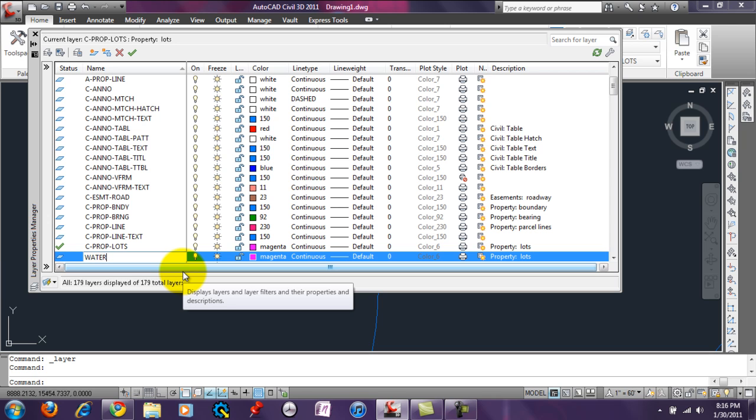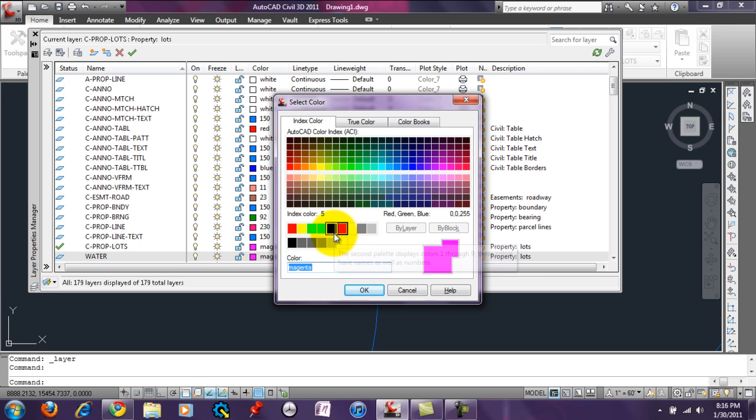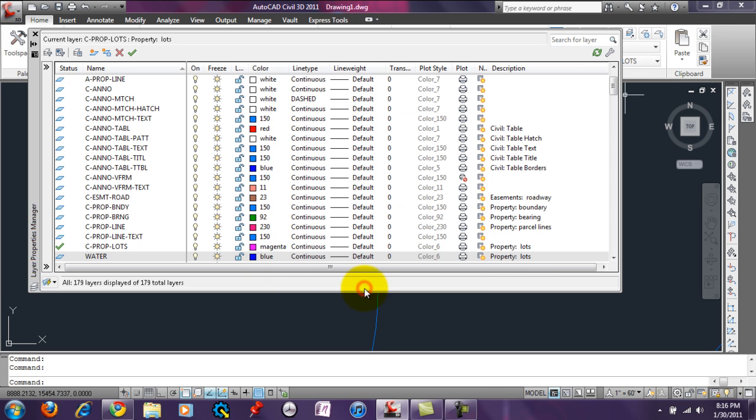I'm going to show you how to create layers in the naming scheme that I'm familiar with. I'm not familiar with the National CAD Standards naming scheme. So we're going to use the ones I'm familiar with. And in your homework assignment, you will create several layers according to this naming scheme I'm familiar with. And then you can select here whether you want it on, frozen, and let's keep it on and thawed out. And then pick the color. So for this color, for water, we're going to make them blue, okay?